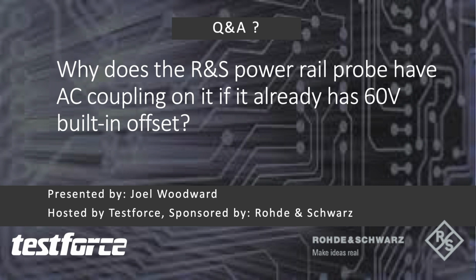The next question is, why does the Rohde Schwarz power rail probe have AC coupling on it if it already has built-in offset of plus or minus 60 volts? The AC coupling is an optional control that a user can set on the probe. And what it allows the user to do is quickly move from rail to rail to rail and to measure noise and ripple without worrying about drift. So it's a little bit easier. You don't have to scale the waveform on the scope. You can quickly move it around to see what's happening there.